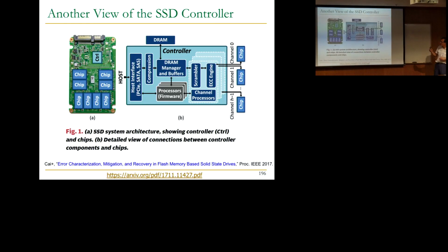And this is a better picture of this. I should have used that picture maybe. As you can see, there's also DRAM actually. There's also a DRAM controller inside the flash controller because there's a DRAM buffer to manage the mappings and to manage the writes internally. So it's not just the flash controller, but also a DRAM controller inside it. It's fascinating to look at this.